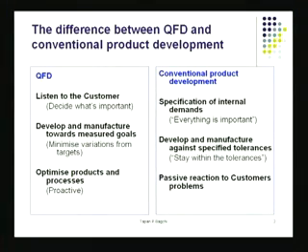Let's look at the conventional approach to designing a product. You start with what we call specification. If it's a pen, what are its specifications? First of all, let's look at the two parts. We have the cap, and the cap has a clip. If you look a little closer, the clip has a little tolerance, so some numbers will have to be given there. There's a length of that clip. Then at the top of it, there is a certain curvature that perhaps gives it some aesthetics. Then you look inside, there's a hole, and the body has to go in there. That fit has to be airtight so that the ink doesn't dry out when the cap is on.